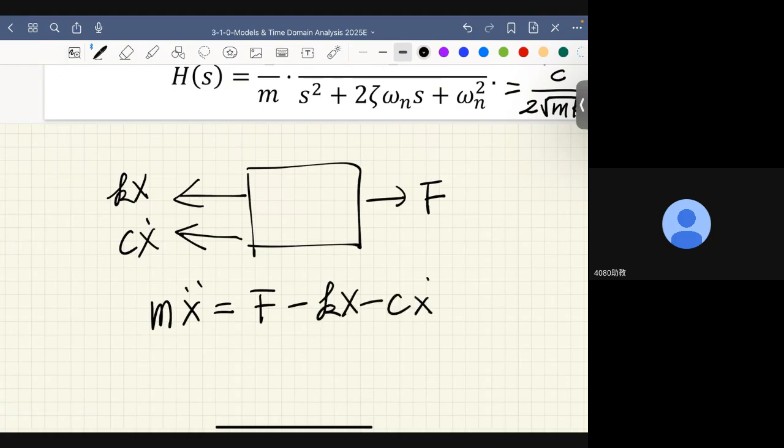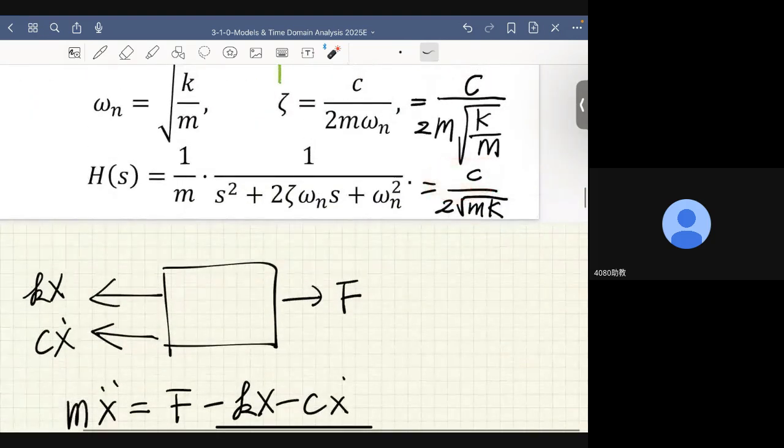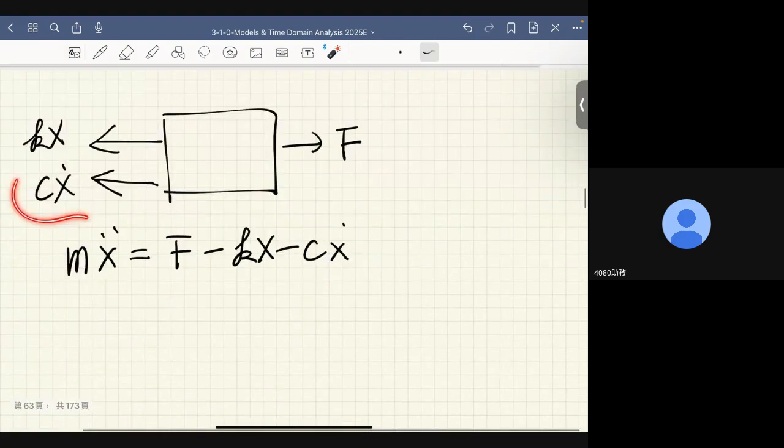So if this is the case, the damping ratio is what you want to use to characterize the damping effect. Now, in absolute terms, this is of course the damping force, right? But how large the damping effect really is for this system depends on two other factors. The first factor is K. If K is very large, then you have a large spring force.